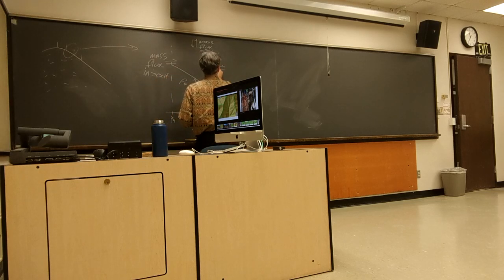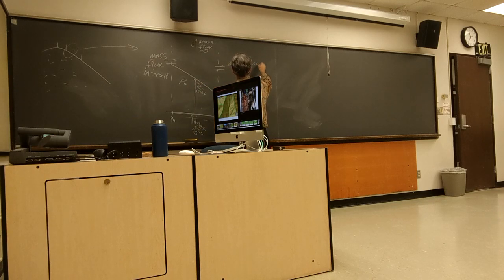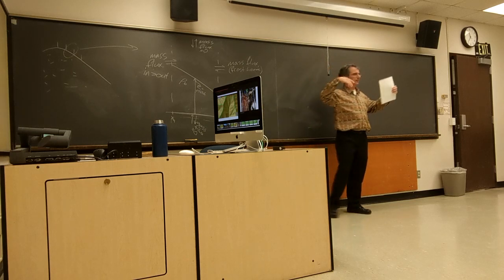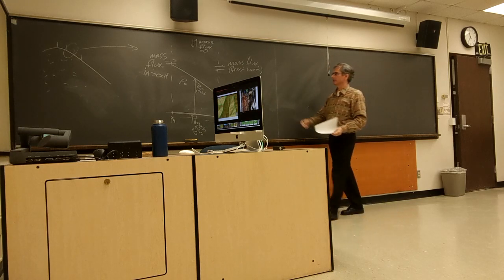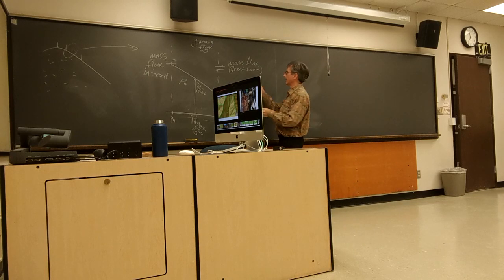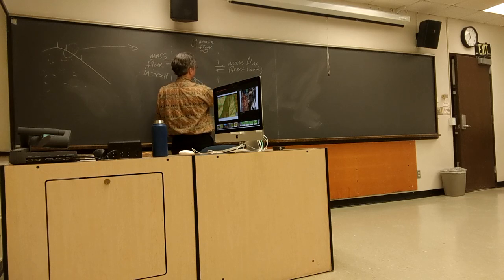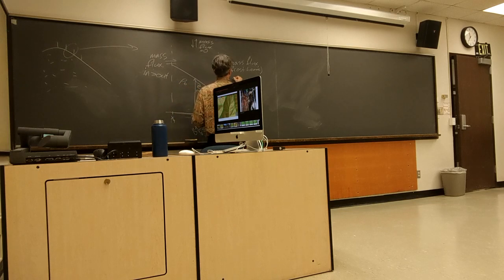And on this side, again, we've got another mass flux. And again, likely due to frost heave, but could be some other things as well. I'm just thinking in terms of a moraine sitting up on a mountain at elevation, frost heave might be important. But again, here we're going to have an imbalance since we've got this relatively steep slope, but in this case, more going out than coming in.